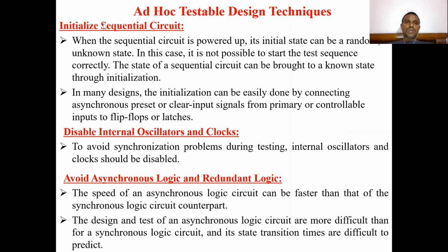So that's the second technique we have in terms of sequential circuits: initialize the sequential circuit. In many designs, the initialization can be easily done by connecting asynchronous preset or clear input signals from primary or controllable inputs to the flip-flops or latches.